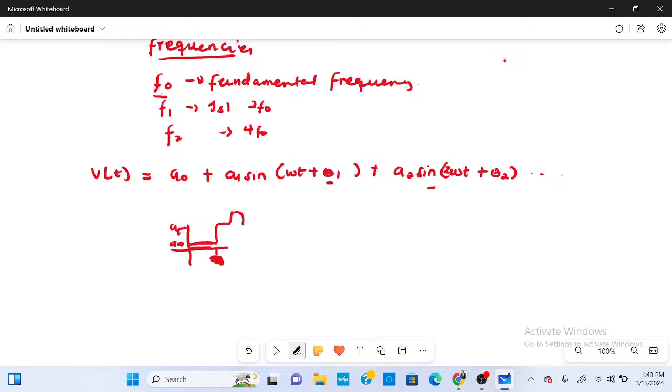How do we find the root mean squared then? Under normal circumstances, root mean squared is the peak voltage or peak current over square root of 2. But in this case, you draw your square root, then you find the RMS for each waveform. So the RMS for this, we just square it, A naught squared, plus, what's the RMS for this?